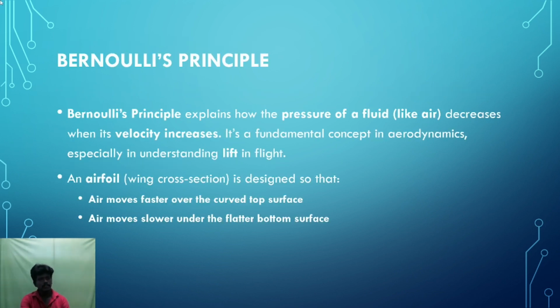Bernoulli's principle. Bernoulli's principle explains how the pressure of a fluid like air decreases when its velocity increases. If the fluid velocity increases, automatically the pressure will decrease. If the velocity of the fluid decreases, the pressure of the fluid will increase simultaneously. It is a fundamental concept in aerodynamics, especially in understanding lift in flight.